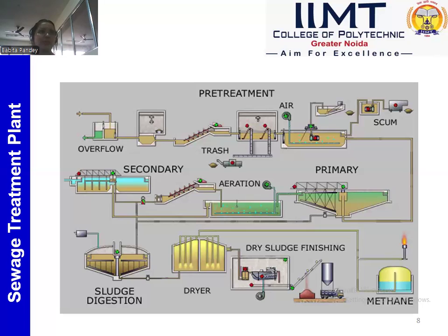Some of the biological component will be there, but it will be moved again through the process by sending it again to the previous tank. The same process continues. So we are now left with only chemical organic matter. For that chemical matter, we will add chlorine as a disinfectant and we will clarify the sewage. And the sewage which has not been clarified is again sent through the same process, by the first primary tank, and the process starts again like this.